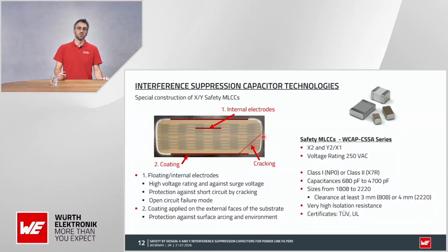In our case, we have a product series called Big Cap CSSA, and we have both X2 and Y2 chip MLCC capacitors, and they are all limited to 250 volt. Now, this is a limitation of the technology, and it's also related to the sizes, because in the end, we are not able to get more than 3 or 4 millimeters creepage.